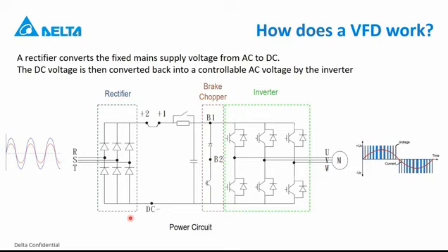You can also use single-phase drives, then you have two fewer diodes on this side. Regardless of whether the input of the drive is three-phase or single-phase, this still gets converted to DC, so plus and minus, and the output is always three-phase. One question which we get often: can we control single-phase motors? And the answer is no. The output is always three-phase, so you cannot use it with single-phase motors.